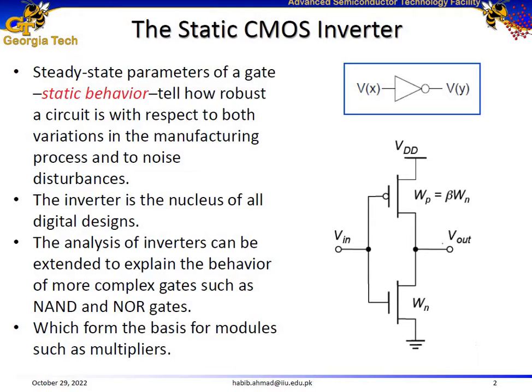Is it going to be P-type or N-type? For an NMOS, the channel is N-type, the drain and the sources are N-type, but what is the substrate made up of? It's going to be P-type, right? For an NMOS, the substrate is P-type.